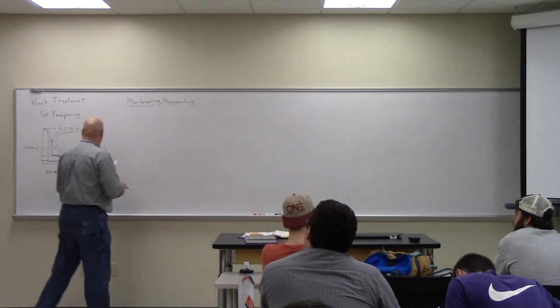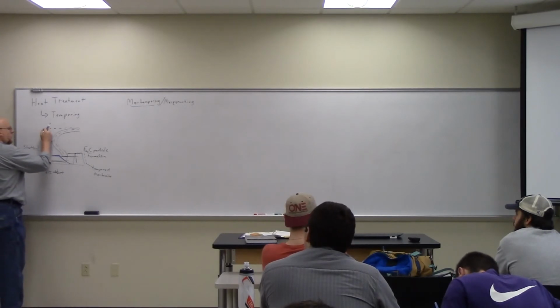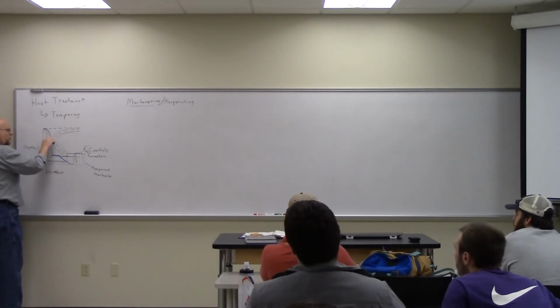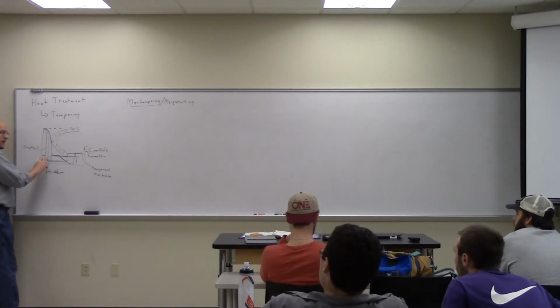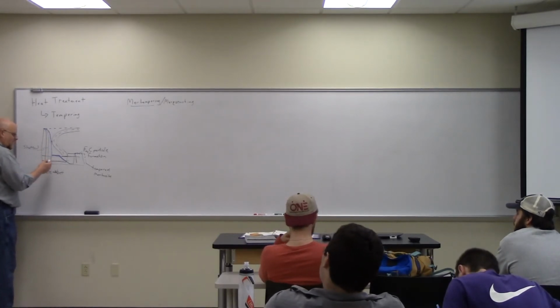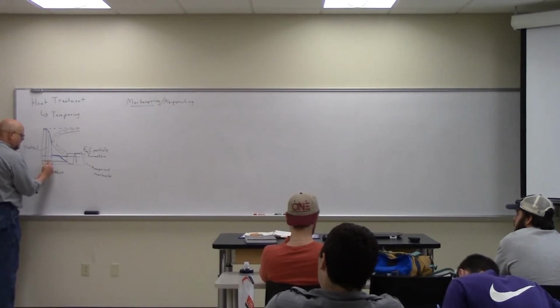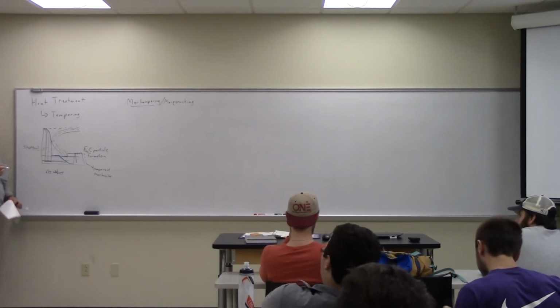Because in reality, if I draw the surface is going to quench like this, the inside is going to quench more slowly. Right? There's going to be a difference between the surface and the inside. So there's going to be a point in time, in this interval of time, the surface is brittle, but the inside is not. And so again, that's where the shattering comes from.